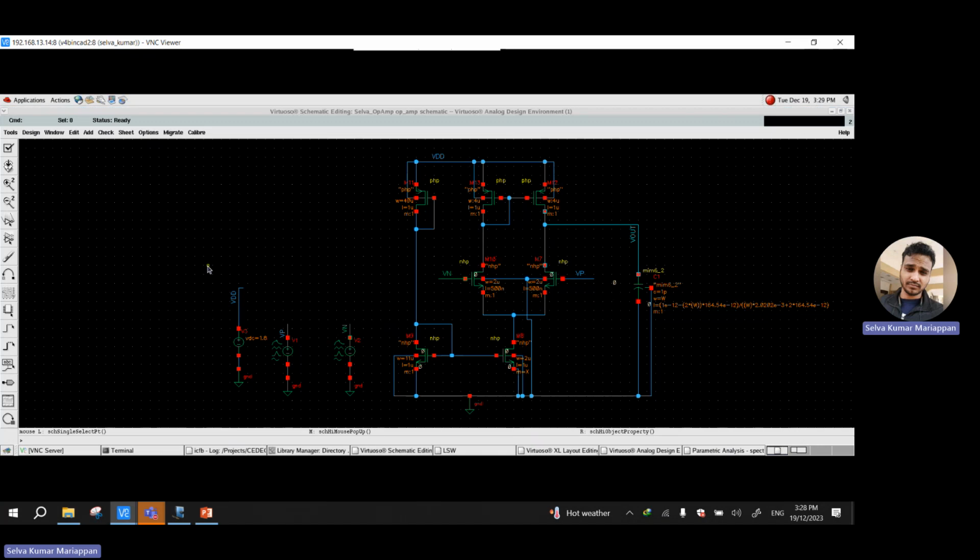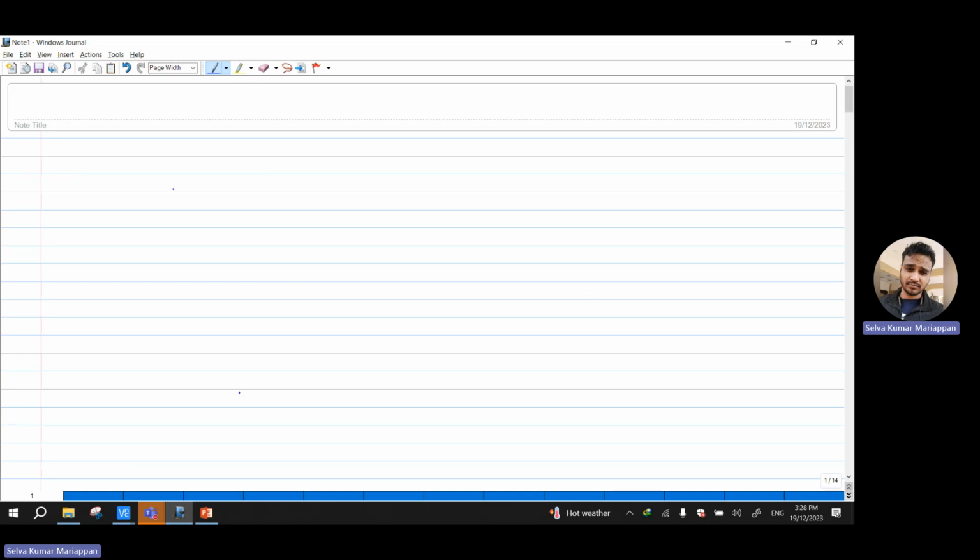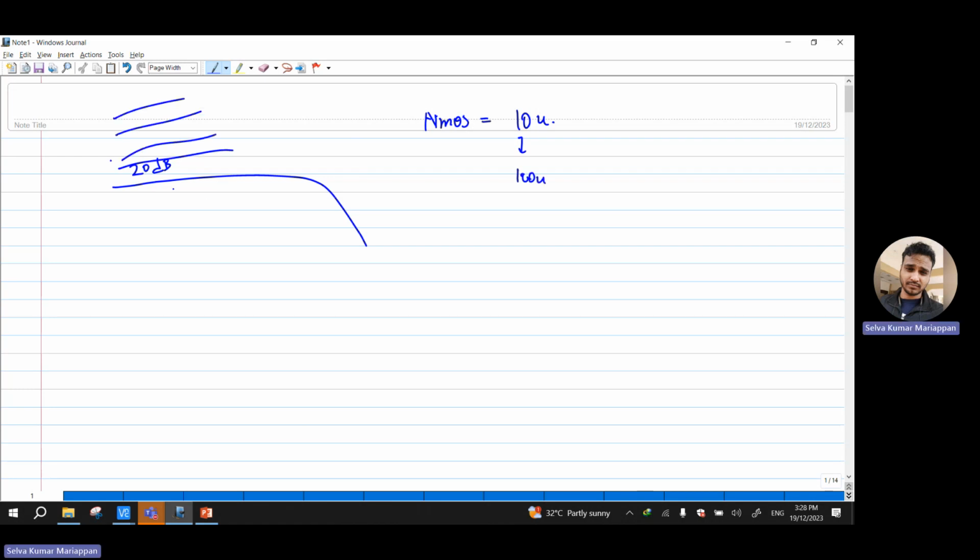Let's say you want to tune, for example, you want to get your gain, right? You have your gain, okay. So let's say for one of the NMOS that you set, the size you gave was 10 micro, and you are getting a gain of, let's say, 20 dB, and you want to increase and increase and increase, right? So you can just sweep this one from 10 to 100 micro and then check how your gain behaves in just one single sweep, okay, and you get your maximum.